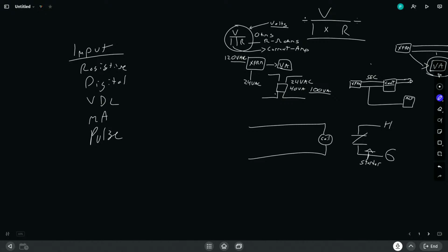Sometimes the controllers actually have their own power. And milliamp is very similar in that you pretty much wire it up the same. There is a little bit of nuance on some controllers that involves resistors and doing things a little differently, but for the most part, it's wired up the same as well as sourced.